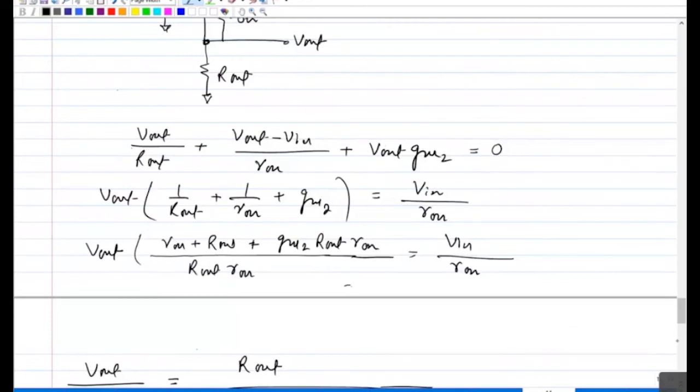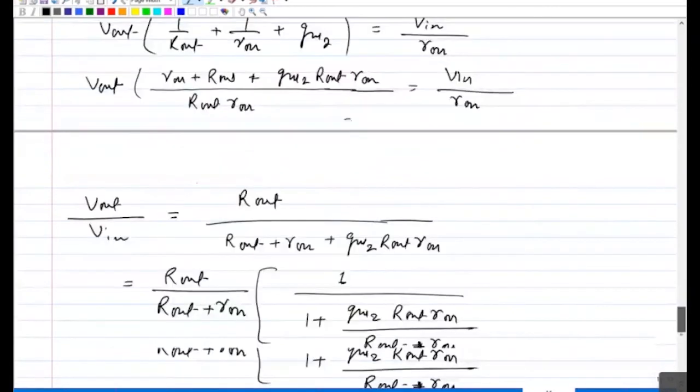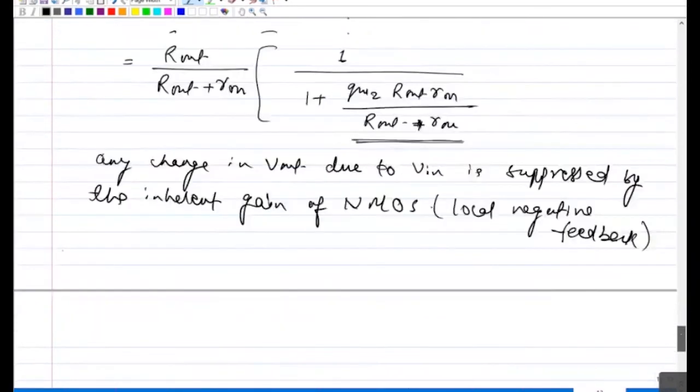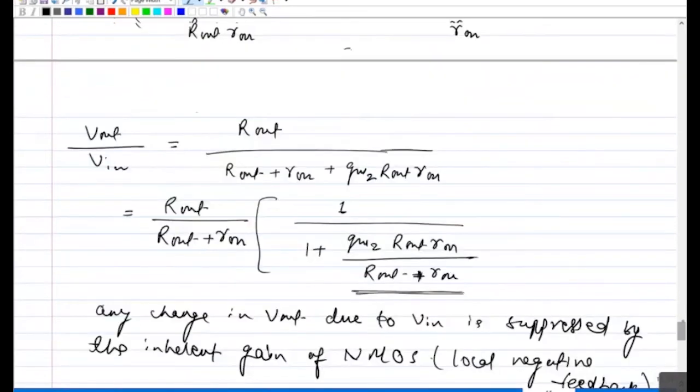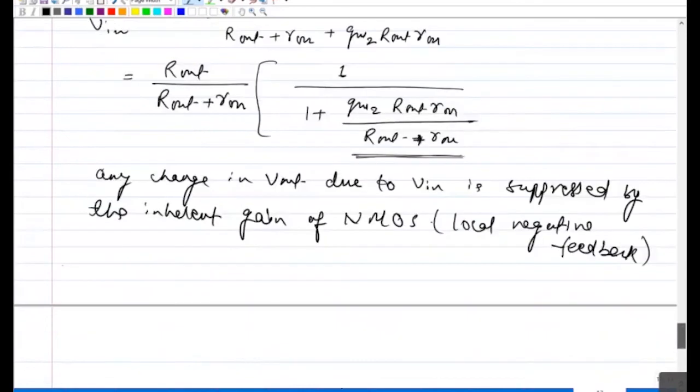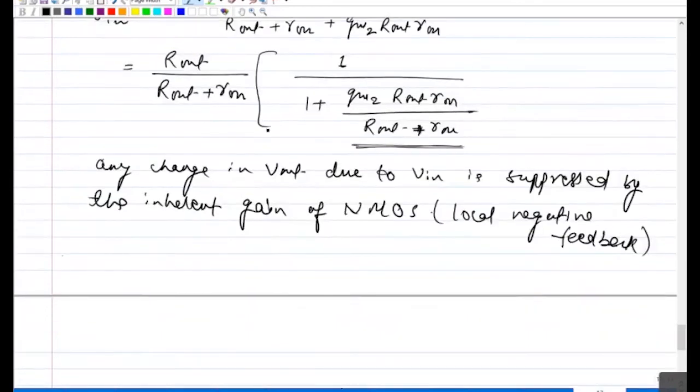And we were saying that your second stage will have no impact on your PSRR. That was mainly because of your GM component. So in the DC here, if you say it is suppressed by 1 over GM R out, but this component is already less than 1, you can say that even at DC you are starting with a better PSRR.